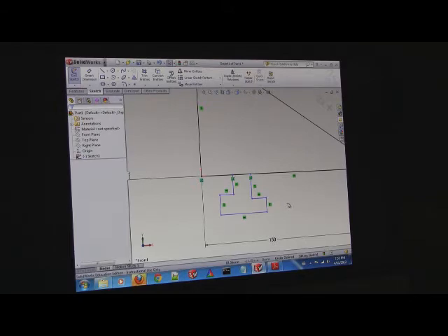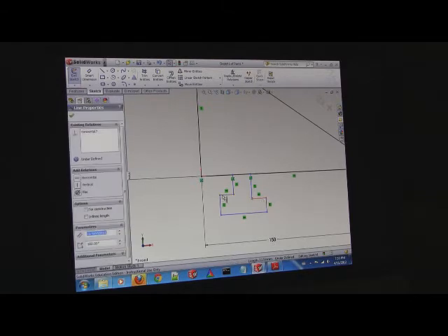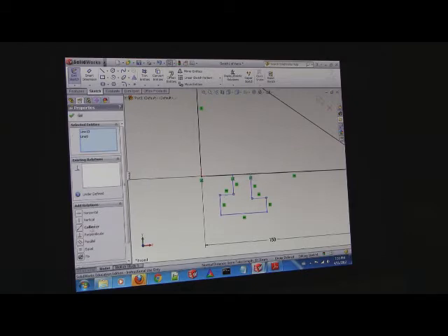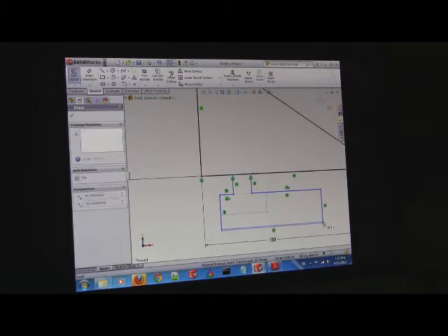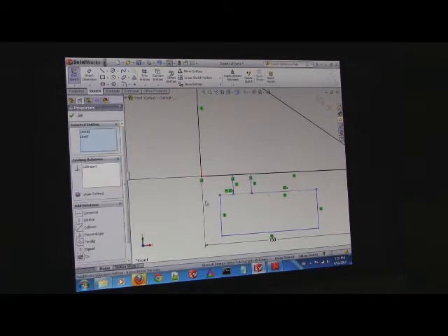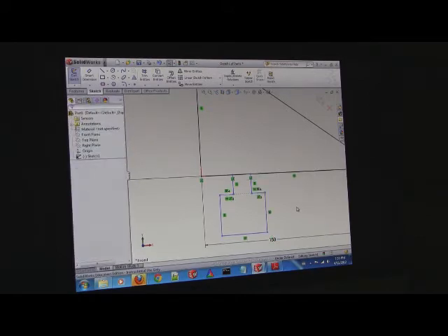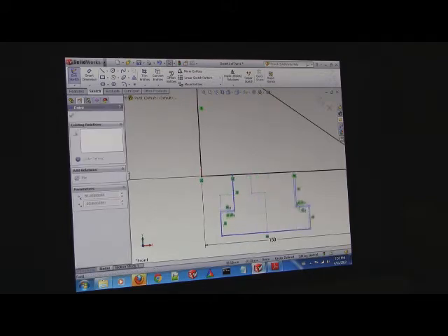Okay, this is how you make your life easy in SolidWorks. Keep watching me. I select this line and I press collinear. Boom. Awesome. So now we can drag this around, but you see how this distance here is longer than this distance? Press this line, and press equal. Boom! So this is the trick, and I forgot to mention this in the original training. Collinear and equal I use more than any single other thing in sketches when I have lines. Now watch when I drag this around, it's the right shape even though it's not the right size.